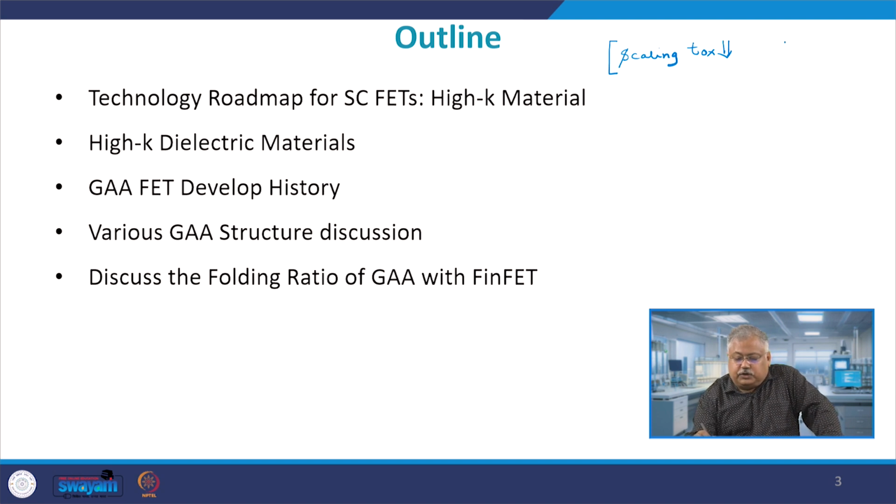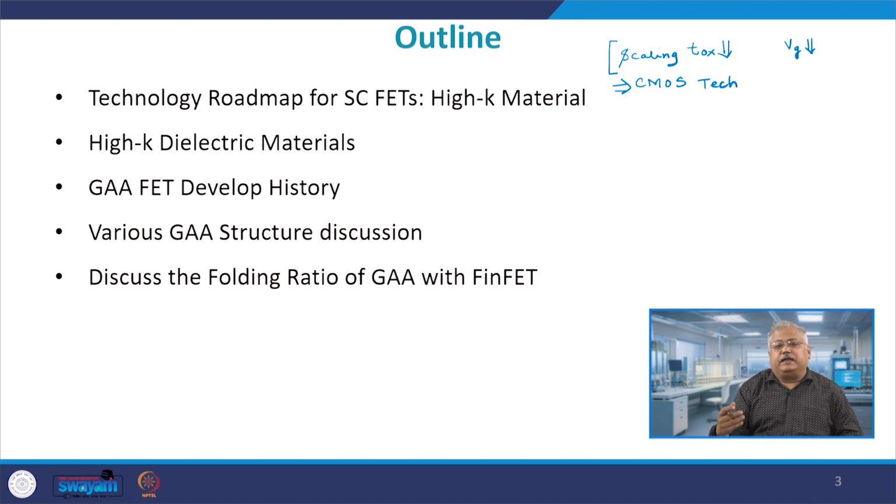So, what you do is that you scale down your gate voltage, but then you need to scale down your T oxide, so the electric field remains almost constant, and that is the reason you require to have these oxide materials being made shorter and shorter. And this is an effective approach in all your CMOS technology.